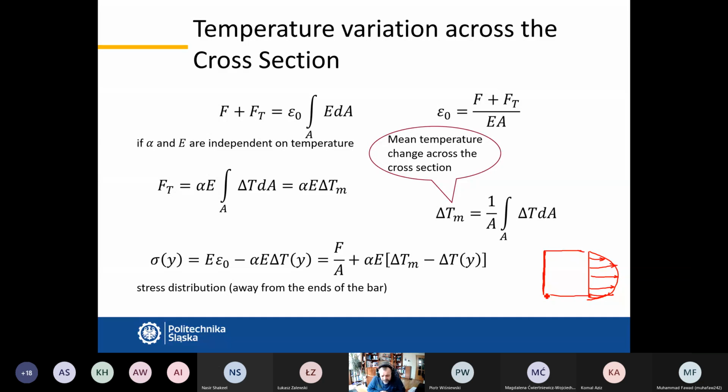according to the Saint-Venant principle, we should be at least about the distance of the height from it. Let's say if this height is h, this is true if we are about 1.5 h away from the support. The distribution given by this formula will be okay. If we are close, this is not the story.